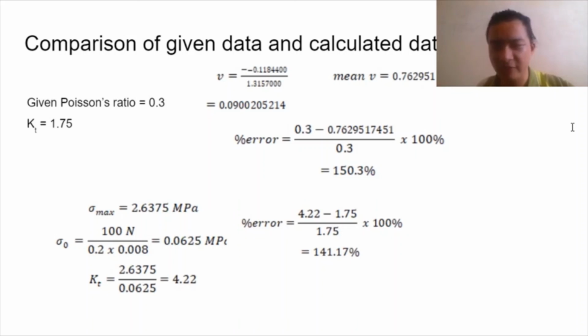Besides displacement at the fixed support, all other calculated parameters were not consistently converging as the number of elements increased. It is noted that although the consistency generally increases with the increasing number of elements, the result might still experience a spike due to the number of elements being unable to match the geometry in a more precise manner compared to a lower number of elements.